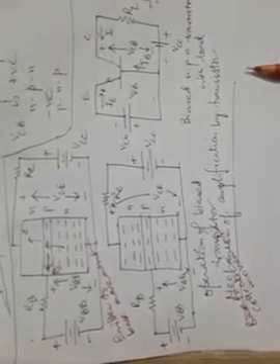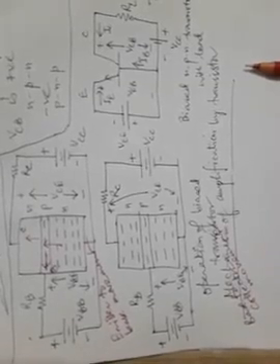The chances of recombination will be there at the base area between the electrons and holes existing as majority carriers, but because of light doping of the base area with the majority carrier holes, the recombination will not be that high.